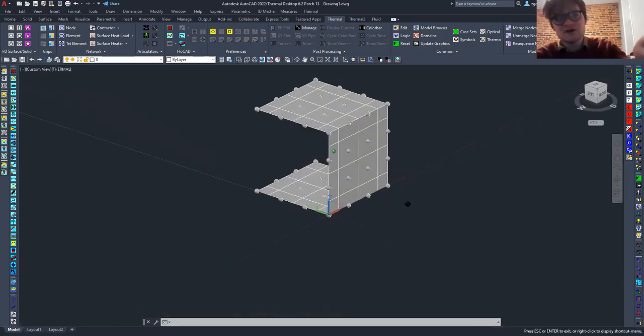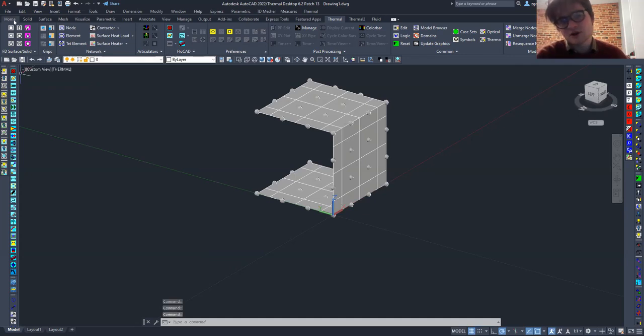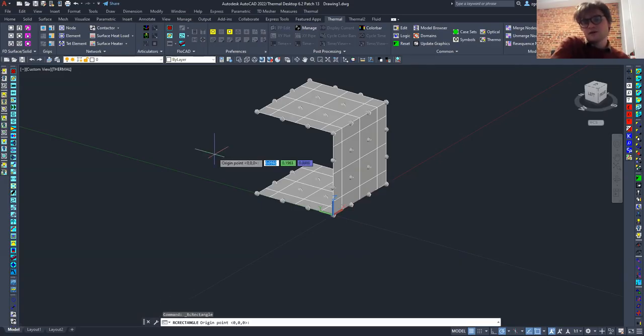But the long way to do it is just to click the rectangle again in the top left and basically go through the motion. So for your next point, you want your next coordinate not to be at 0, 0, 0. You actually want it to be at 0, 0.1, 0 because you want to grab that left corner there.